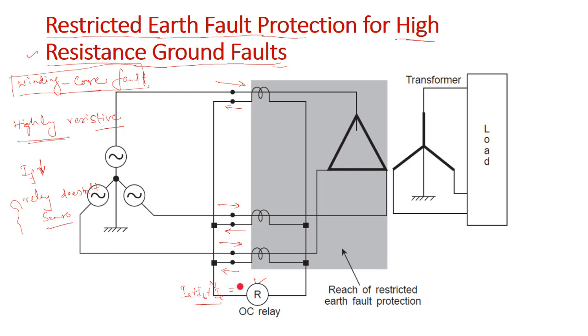So this will in fact be 0 all the time, whether it is a balanced or unbalanced condition, it doesn't matter, because this is a delta winding. So therefore the sum of the currents IA plus IB plus IC will always be equal to 0.